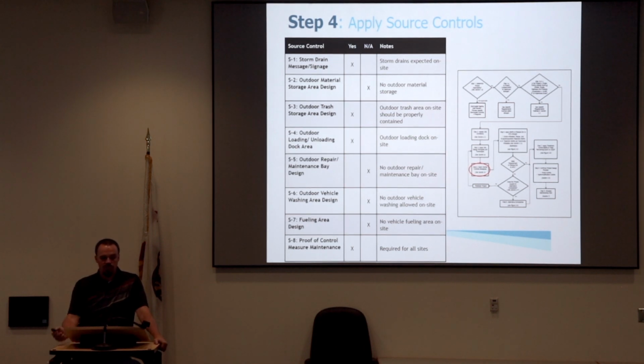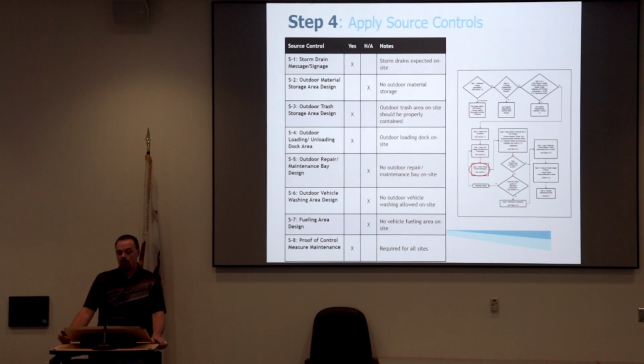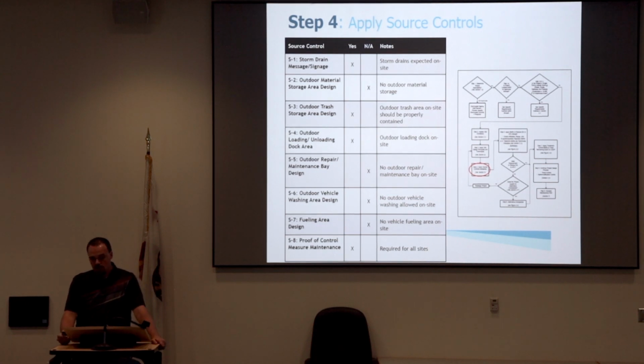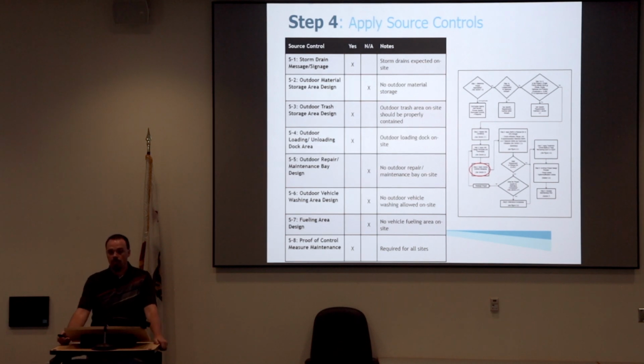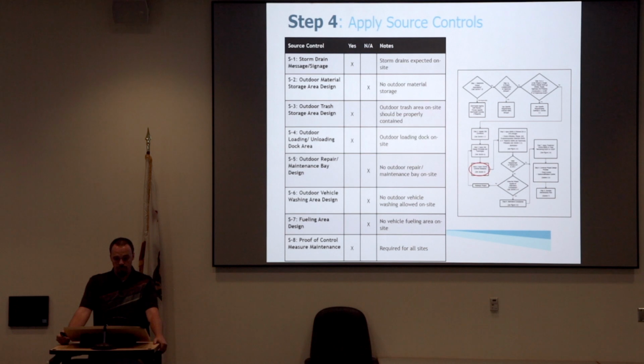So there are specific fact sheets identified in the technical guidance manual of how to design those, and those should be discussed or shown on your design plans. It's rare when they're included within the drainage reports, but it's always nice to have it. Number 1 there too would be storm drain stenciling. Any site that redevelops should have either placards or stencils identifying don't dump to ocean, as part of the public education outreach for the programmatic part of the MS4 permit.